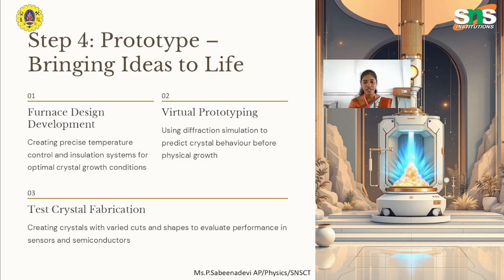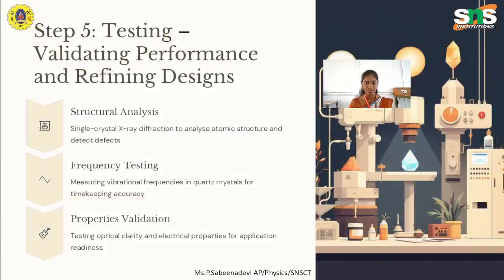Next is virtual prototyping, using diffraction simulation to predict crystal behavior before physical growth. The behavior of the crystal before physical growth can be monitored by virtual prototyping. Next is test crystal fabrication: creating crystals with varied cuts and shapes to evaluate performance in sensors and semiconductor devices. These are all the prototype part.